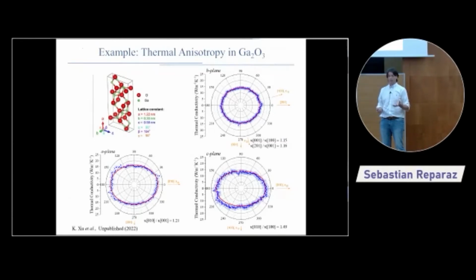So the idea of rotating the heat source or the sample is obvious. Basically, you have access to an infinite number of angles within the surface of a material. And so self-consistently, you can determine the in-plane distribution of thermal conductivity, and what is more important and more precise is that you can determine the anisotropy factor in the case of orthorhombic materials or cubic materials, okay?